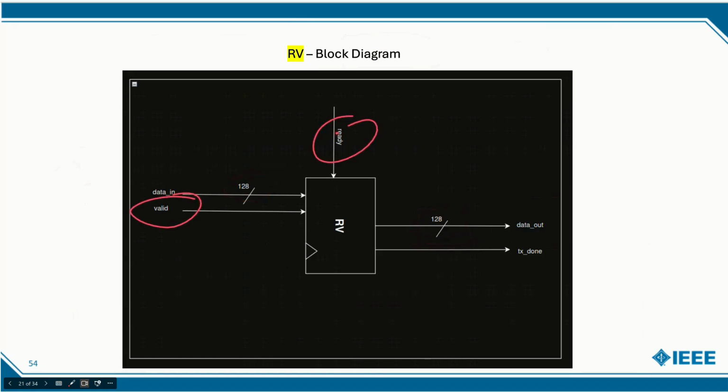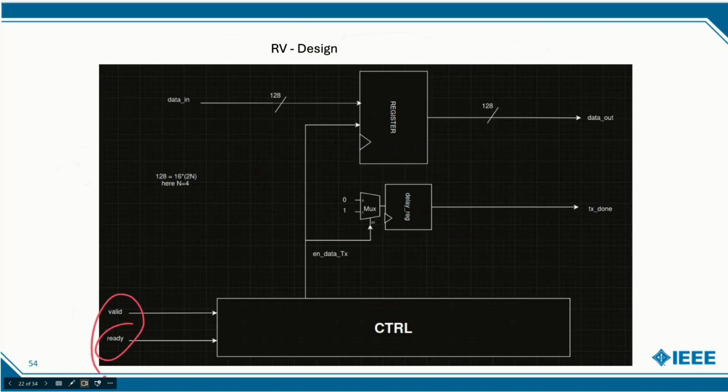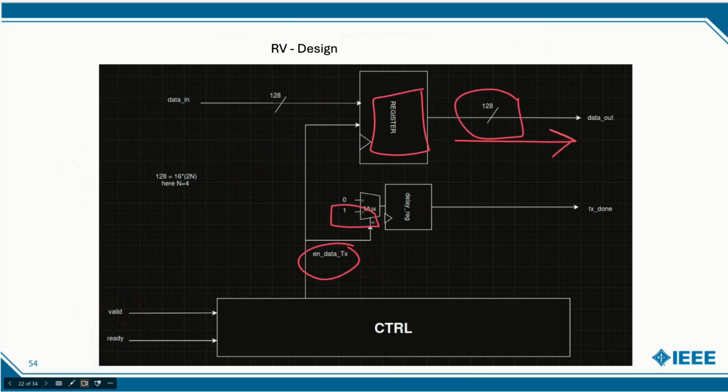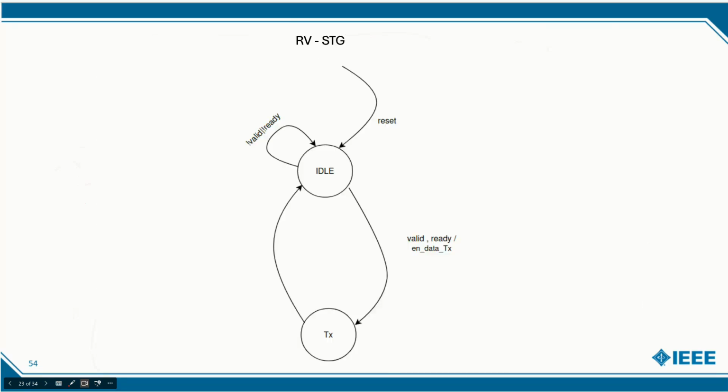When both signals are high, we have a signal called enable data transfer. It becomes high, and the exact value of data goes into the register, which on the load side will let the data out. Also on enable data transfer, we will make all masks high and we will send a transfer done signal, which indicates that we have received the data. And it's the SRC which operates on the same principle I stated earlier.